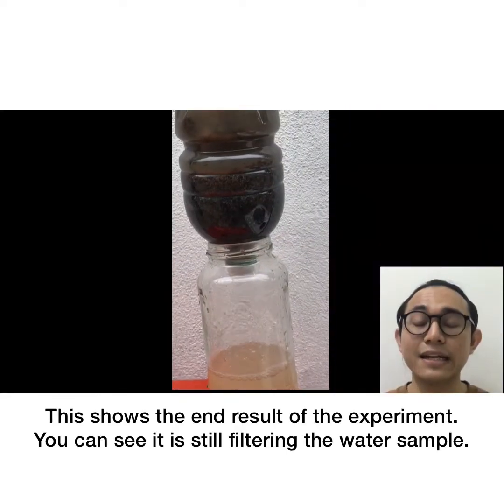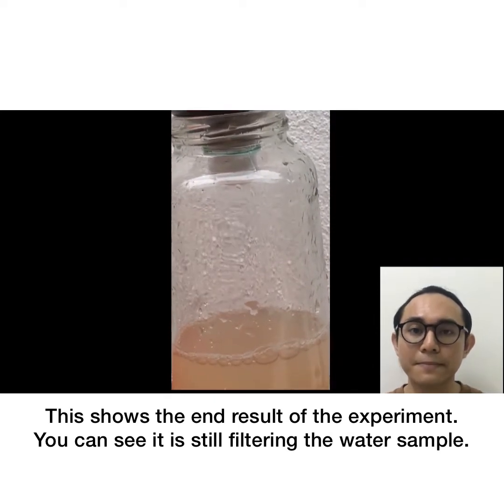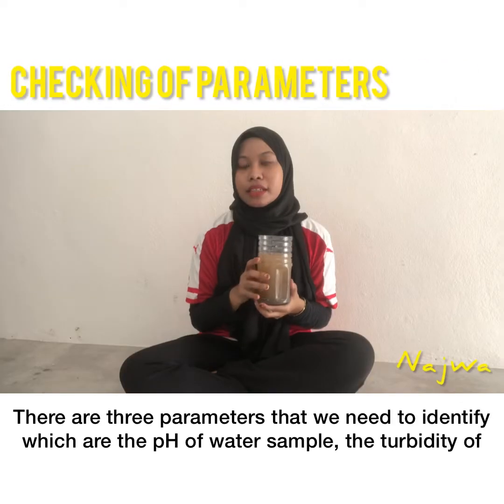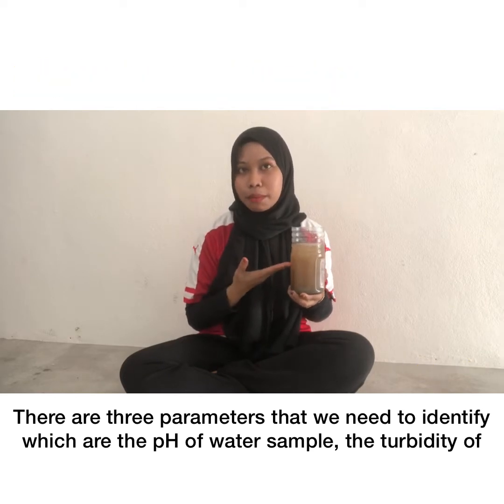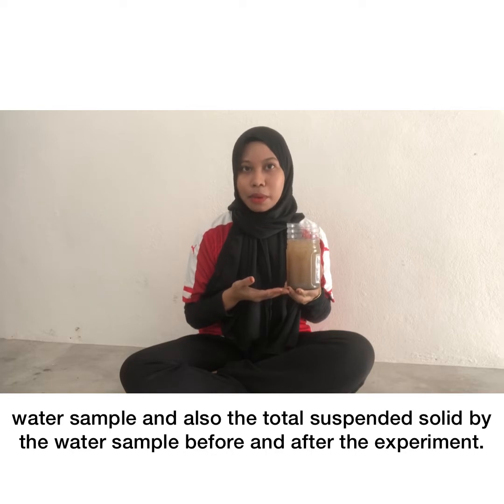This here is the end result of this experiment. You can see it is still filtering the water sample. We will repeat this experiment explained earlier using different thickness of coal. There are 3 parameters that we need to identify, which is the pH of the water sample, the turbidity of the water sample, and also the total suspended solids of the water sample before the experiment.